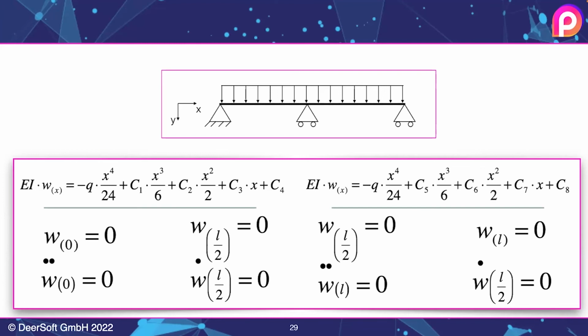You can go on. I've printed all the information, all the values that we know about this system, and it gives you an idea on how to calculate this. The most important part that you need to take out of this is that the actual deflection, the actual loading figure of the system, depends only on the trimming of the trusses. So if you don't level your trusses accordingly, you run into a problem and you don't get the results that you want.